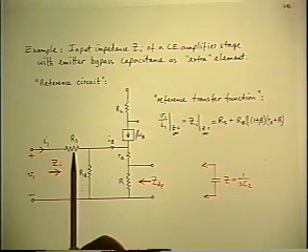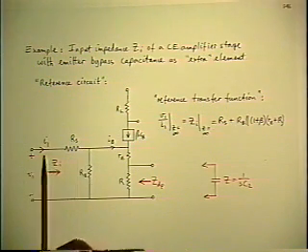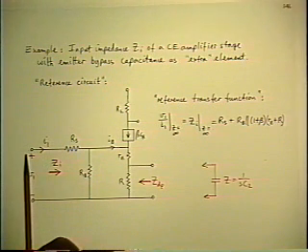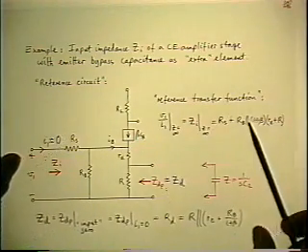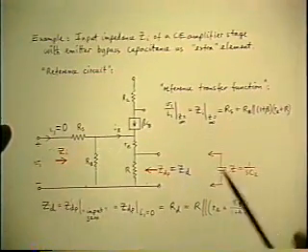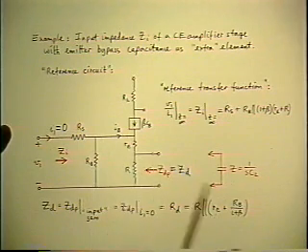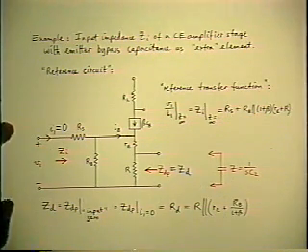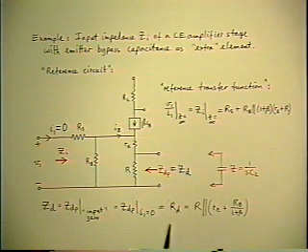Only RB. The RS isn't going to come into it because RS is dangling. The other end is open when I1 is 0. So the condition for ZD is I1 is 0, which means an open input, and the answer is R parallel RE plus the reflected RB. So that's the first driving point impedance.